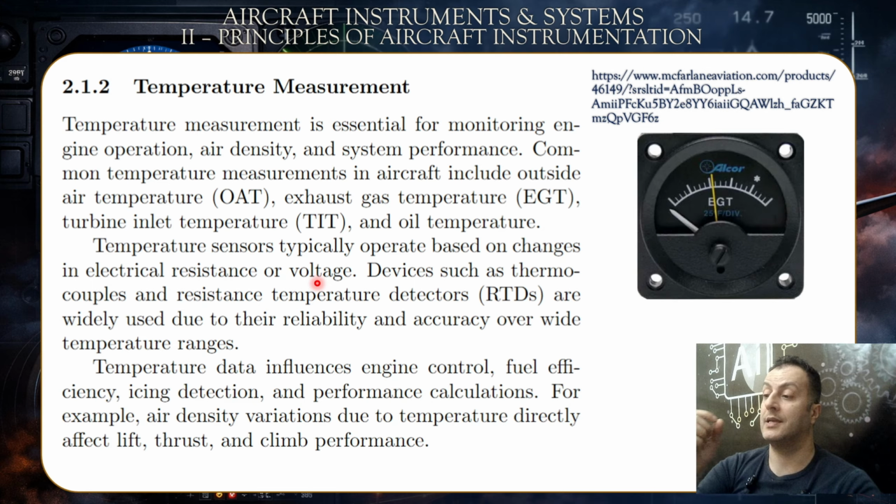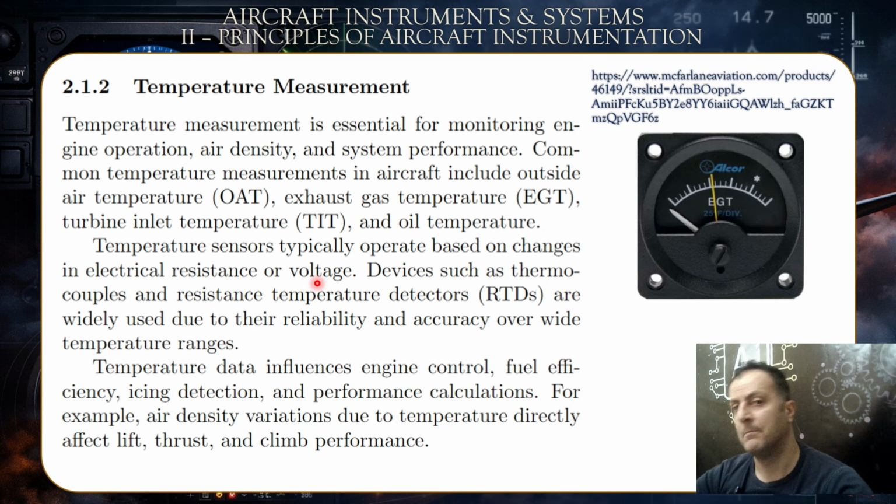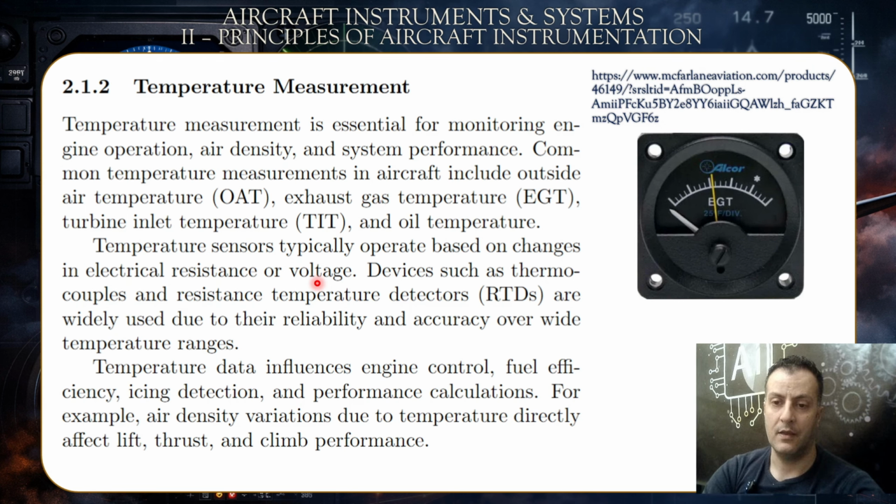But when you have it snapping completely and completely cut, it means that you have a fire on board that had completely melted this resistance, and you would get a fire alarm within the cockpit. So hopefully this explains it.